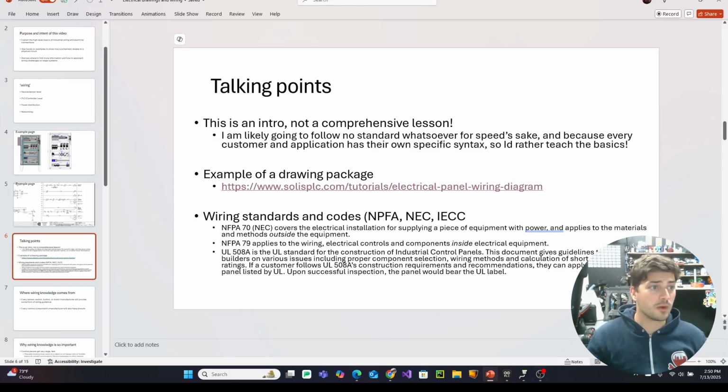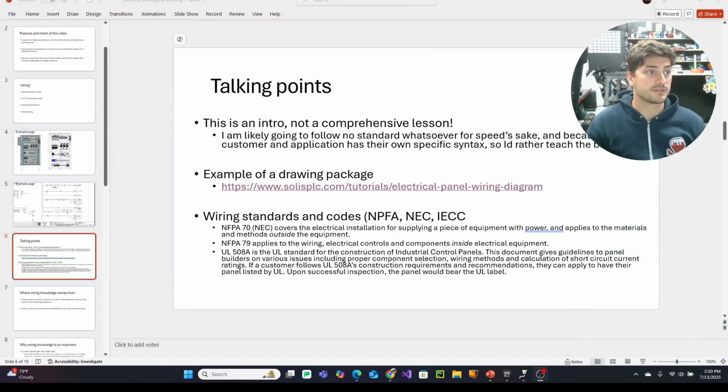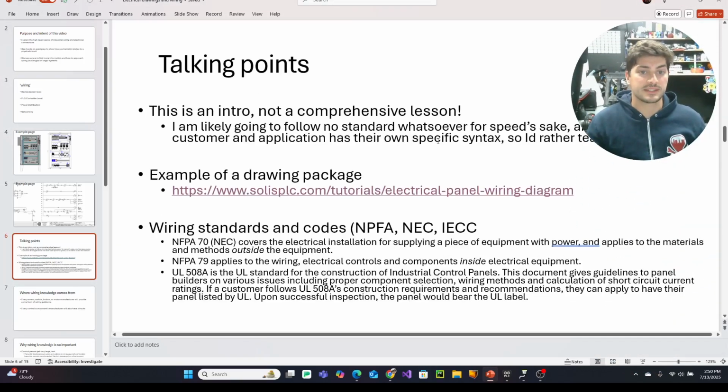But then I do think one thing that's really important to talk about as part of this video is who has standards in this field. So if you're a drawing designer or an electrician or an instrumentation and controls engineer, it's very important to be familiar with NFPA 70, NFPA 79, and UL 508A. Also sometimes called NEC 70, but basically these are industrial guides on power requirements, power distribution requirements, best practices for installing and creating and developing control cabinets.